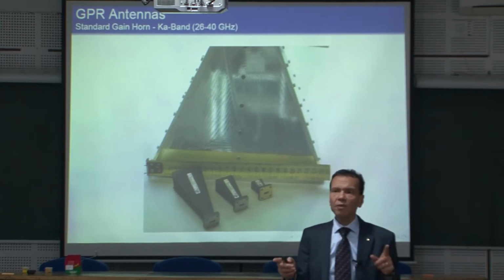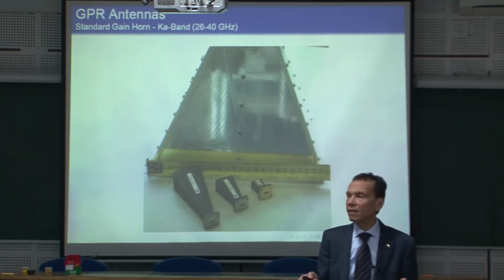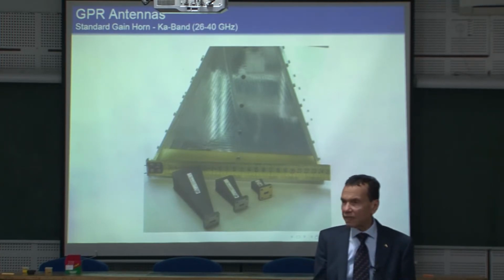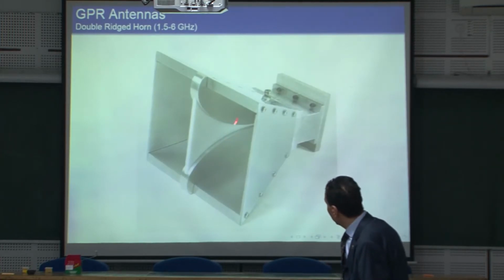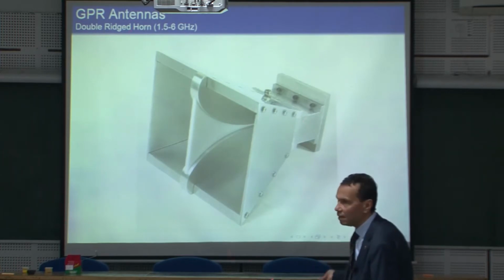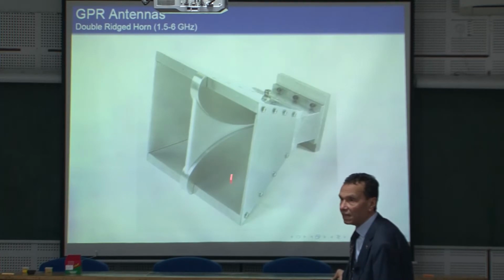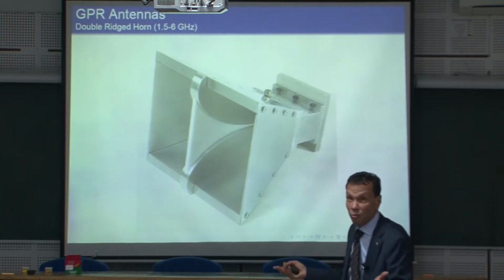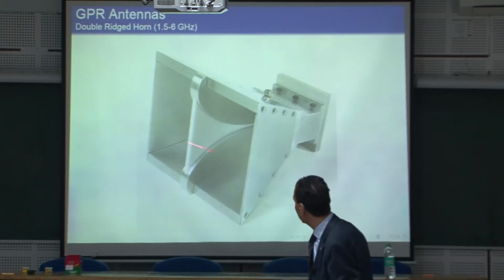But as you know, a rectangular waveguide has a finite bandwidth. If you use ridged waveguide, this one here, the housing here is really not necessary, because in ridged waveguide, the field is highly concentrated between the ridges here. And you guide them additionally by inserting a dielectric here.